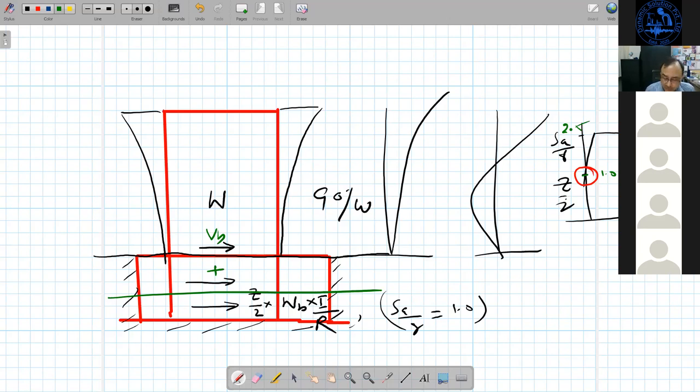Sir, is it necessary that while designing a building, we have to cross 60% of modal mass participation in the first and second mode? If you are not getting 60% mass participation in the first and second mode, it shows that your building is irregular and your modal superposition method is not valid.